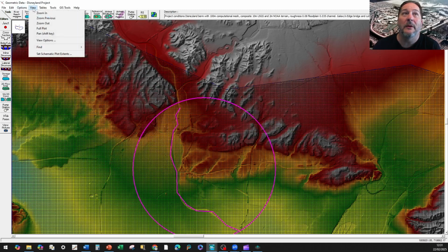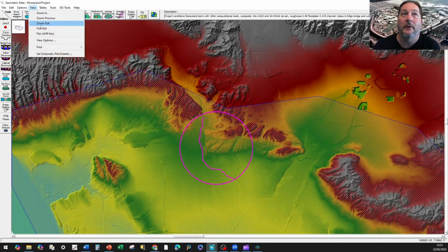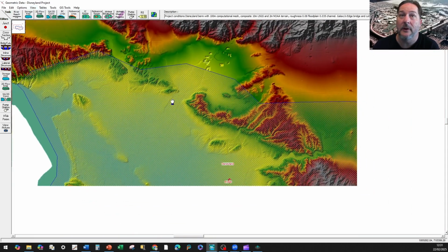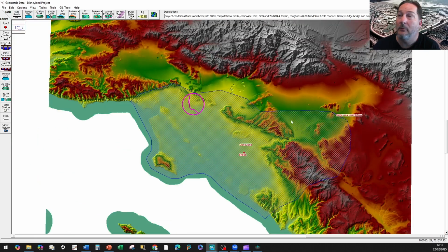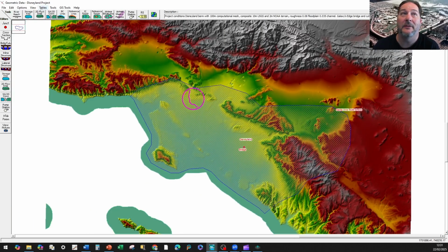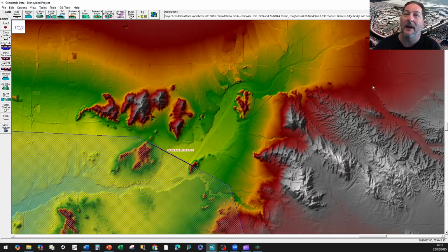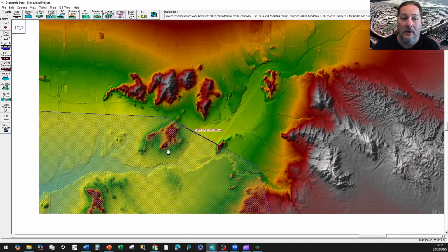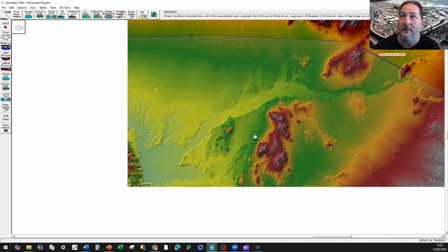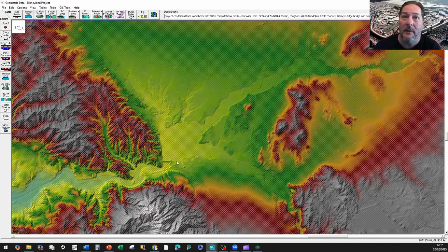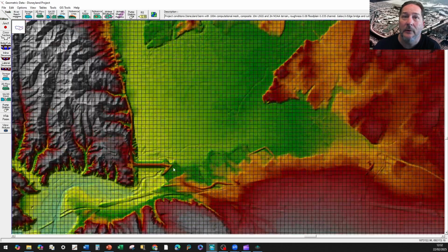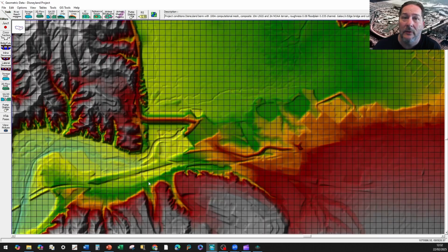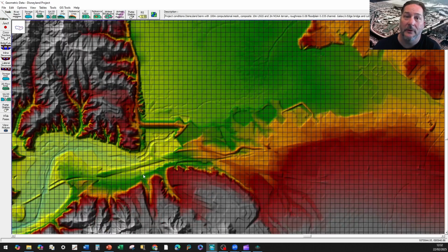So sometimes it's worth measuring those slopes just to get a feel for your energy gradients, because you will need those energy gradients in the end. And we start by estimating those as the bed slope of the channel, even though the energy gradient doesn't necessarily have to be exactly parallel to that. It's a good estimate to start out with. So now let's move into internal boundary conditions. I'll go ahead and try to draw some of these inside. Let's look at the dam itself here, and this is where we'll go downstream of the dam and just assume that a breach hydrograph is going to come in this way.